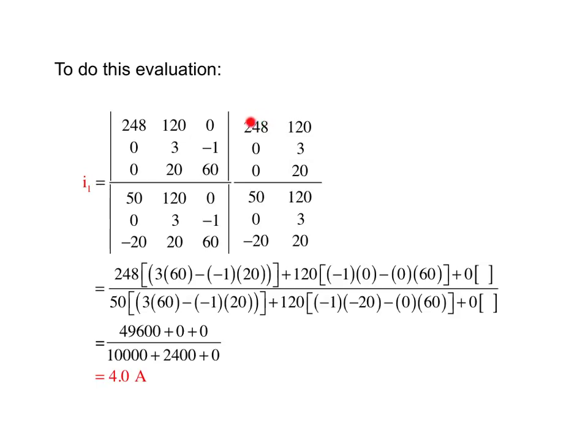Minor point. Notice that we had one loop in which there were voltages and two loops in which the voltage was 0. The reason why we wanted to do that, if you can do that, is that you will get this nice situation where the numerator only has one quantity that's non-zero in it. All the rest have a 0 times whatever and a 0 times whatever. This is why we chose to take the outside loop, even though it had more resistors and more currents in it to hassle with, over having a second loop in which the battery voltages were available.